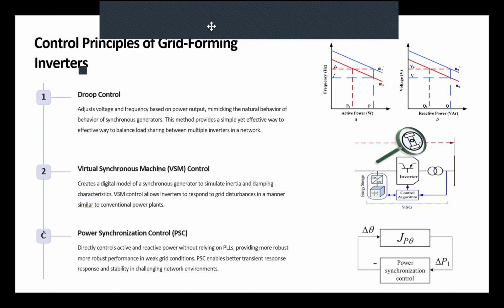So it starts mandating a stronger force over the amplitude of the voltage, compensating the drop of the voltage, or the increase of the voltage in case of higher reactive generation in the grid, and tries to eliminate that effect. So it basically sees the load change, either in active or reactive power, as a disturbance, and it wants to keep the voltage and frequency at the desired level. It sees them as a disturbance and tries to eliminate that unbalance. This is the basic of the droop control.